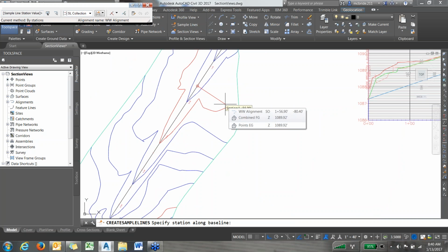Now in grass waterway design, and I have to remember what this is, but I believe that you are not required to put cross sections on a grass waterway set of plans. You are, however, required to do a red line check after it's built of some sort of cross sections every 300 feet, at every grade change, at every individual waterway branch. So there's several spots where you have to do cross sections as checks. You don't necessarily have to put them on the plan. You just have to have them in your survey book.